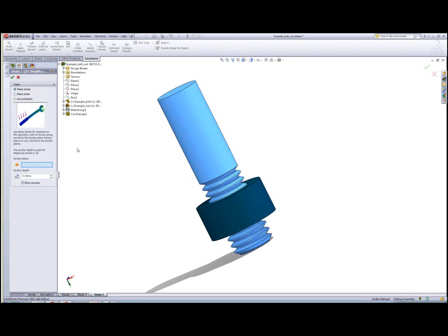Now, if you look at the very top of my property manager, we have 3 different approaches. We can take the plane stress approach, which is actually meant for thin models, where you're not interested in, or there will be no force acting normal to my section plane. Also, we have the plane strain ability, and this is actually meant for models that have thick geometries that extend along the distance of either side of the section plane with no force, again, acting normal to that section plane.